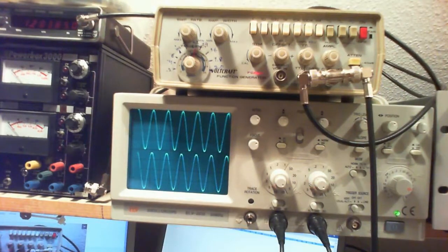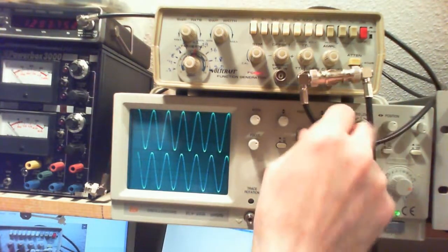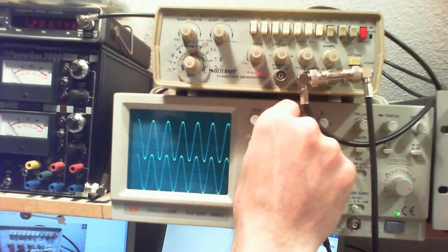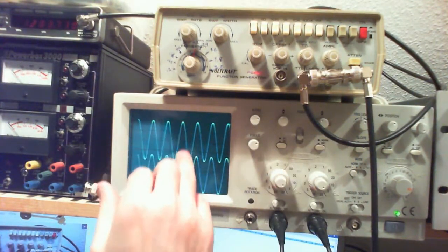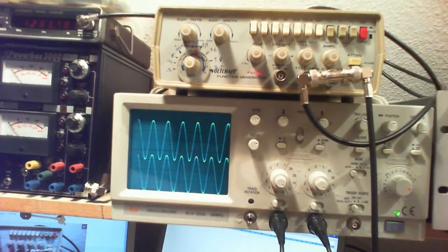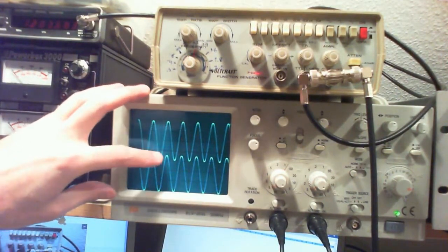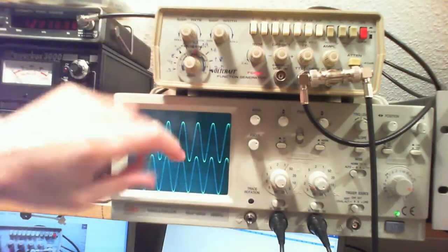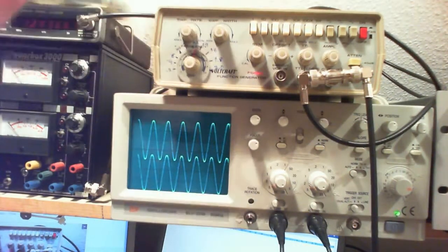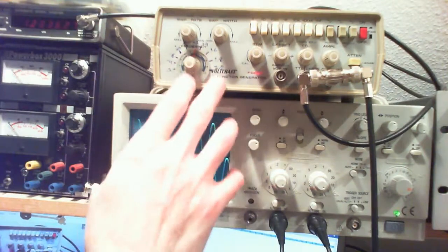19 volts peak to peak, and the frequency is 1.3 megahertz or so. And now you can see that the input has actually changed. The input is 4 times 4, equal to about 20 volts peak to peak. So we started with 19 volts, but as you increase the frequency, your input kind of changes on this generator. It happens on this generator.